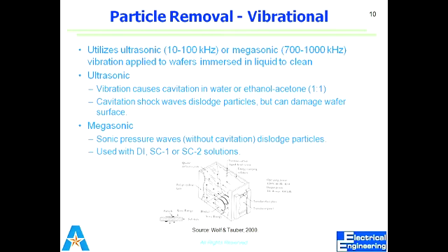At high frequencies, we are not providing enough time for the bubble to collapse. So the bubble does not get enough time to collapse because the frequency is high. So that's why those shocks do not come into account, and we can avoid those. But the rest of the process is the same.